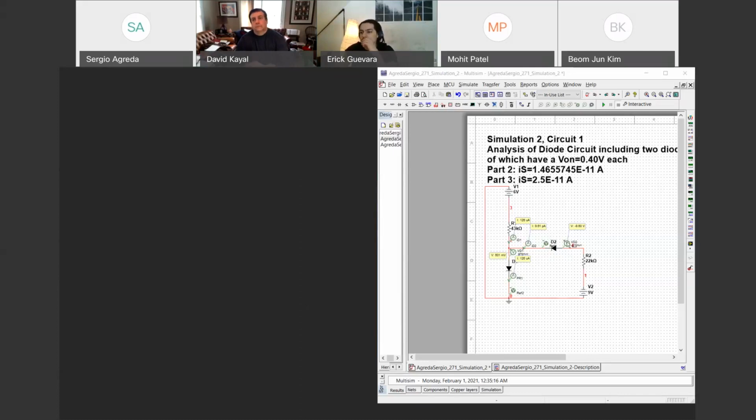He'll also explain about assumptions. You take as many assumptions as you can to get a proper solution. So analytically solving this circuit, we would choose that the first diode, the one that was here, is on, and the second diode is off, which will behave as an open circuit. When the diode is off, it won't have any current running through it. It behaves like an open circuit, like there's no connection and no current is going to run through it. But a voltage will build up between the anode and the cathode terminals.